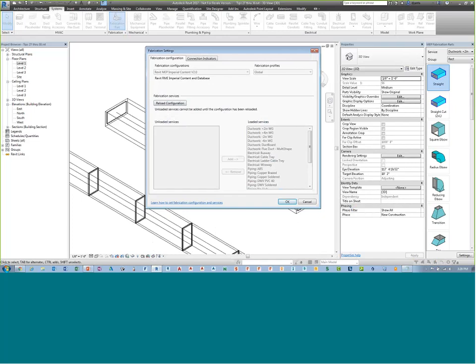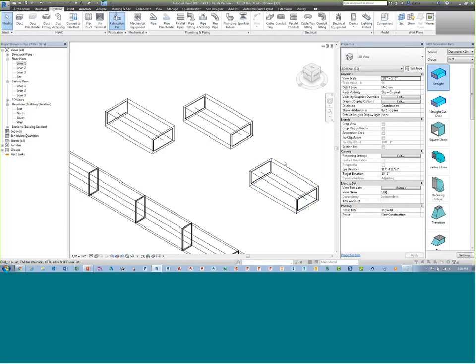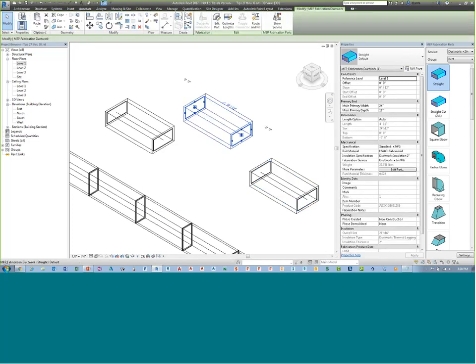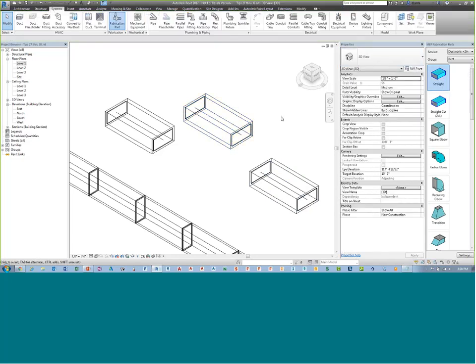And once you reload, that information will show up here when you're working with fabrication and installation specification data. Kind of a workaround right now, but until Autodesk gives Revit the ability to make it on the fly yourself by clicking, for example, edit type and making the changes, that's kind of what we're stuck with.